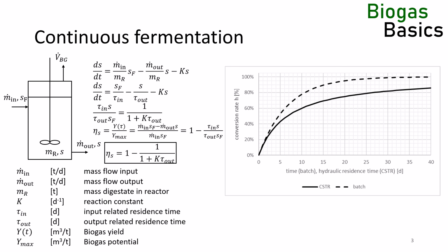On a more academic note, there is one way of using a batch reactor to directly read the conversion in the continuous steady-state reactor, and that is if the continuous reactor is an ideal plug flow reactor. However, this comes with a disclaimer that there are no ideal plug flow reactors in AD. Plug flow reactors will require inoculation, and they struggle to keep their plug because of axial dispersion. I made a whole presentation about it.